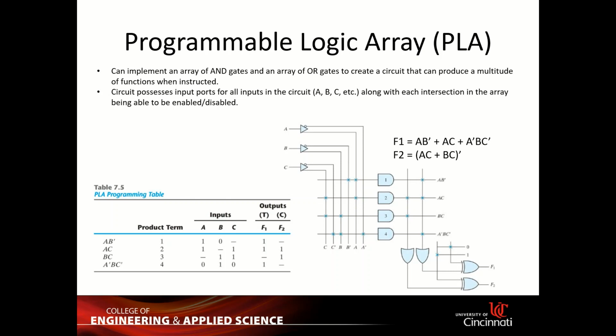So look at this. Okay, if I give you F1, F2, two functions, right? And I give you a plain PLA like this. How can you program it? So in here, this group right here, you can call it an AND plane, which will provide you the min terms or product terms. This one will sum them up. This is an OR plane, which means you sum them up.